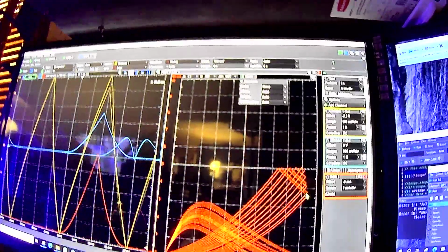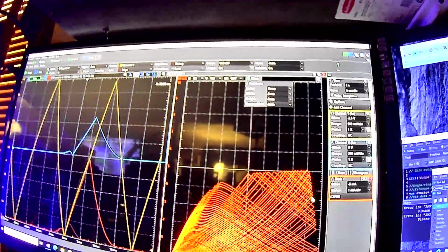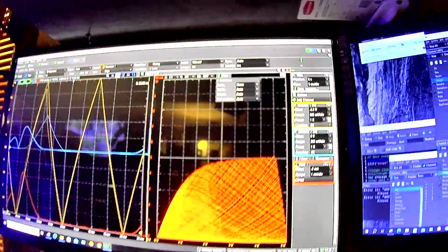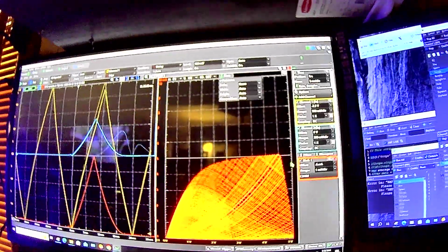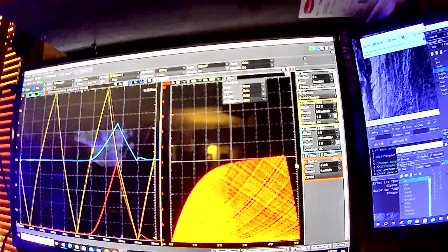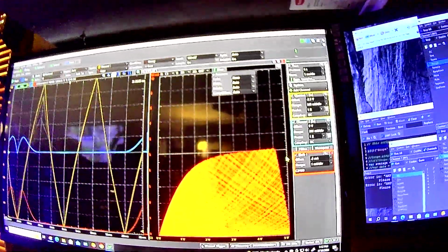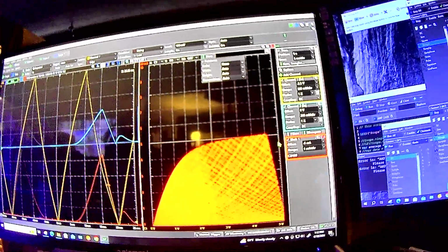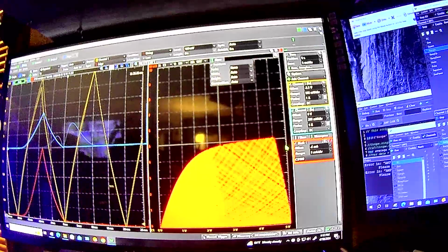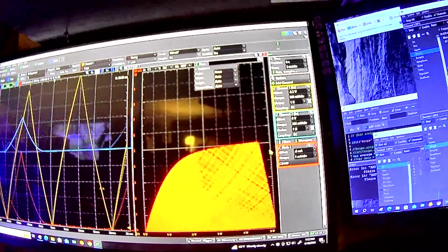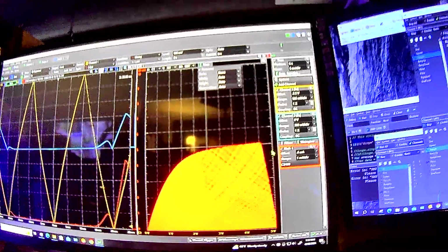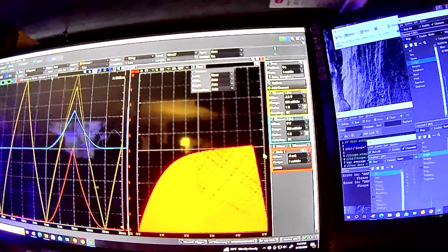But that's why putting that resistor in there was a good idea, because that would have possibly damaged the JFET. Probably not with the Analog Discovery since it can't do that much current, but if you didn't have something like that there, yeah, it might have toasted your device. But at any rate, I just wanted to kind of point that out.